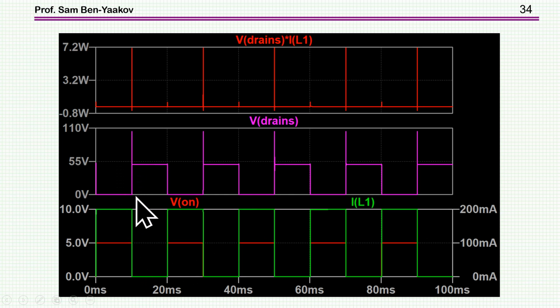Now the two transistors are actually 200 volts together. And here it goes only to 110. And the reason is that they are probably not balanced. And also the energy is probably fairly low, so it really doesn't have to go to that high voltage. So these are the spikes which are not dangerous. Nothing will happen to the transistor if we are not exceeding the energy or the avalanche energy allowed. And we'll see that in a minute.